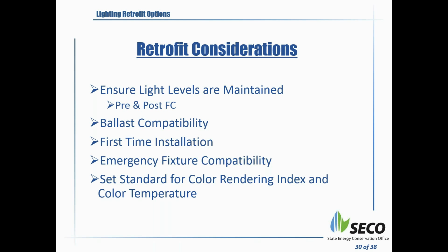First time installation, you've got to be careful, because a lot of times if you put the LED lamp in in the reverse position, you won't be able to tell, and you won't get the light output that you need from it. There are also compatibility issues with the emergency fixtures. So if you've got a battery pack or emergency fixtures in your facilities, you need to test them and make sure that you don't have compatibility issues.